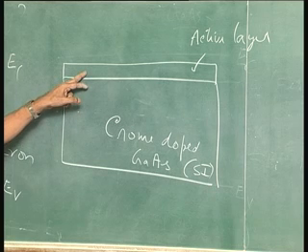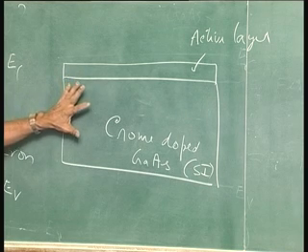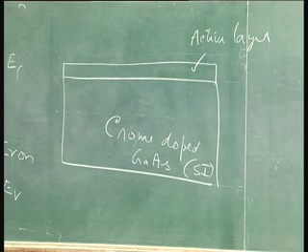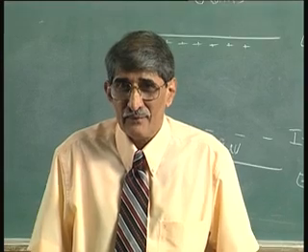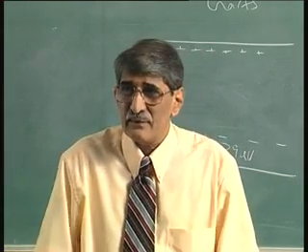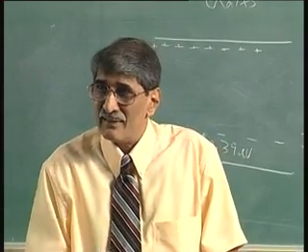You do it at higher temperature afterwards. This has chromium. This one you want to grow at a doping of 10 to the power of 14, 15, 16, that is active layer, N type. Now, when you grow that at higher temperature and do any processing, that chromium gets inside into that layer.